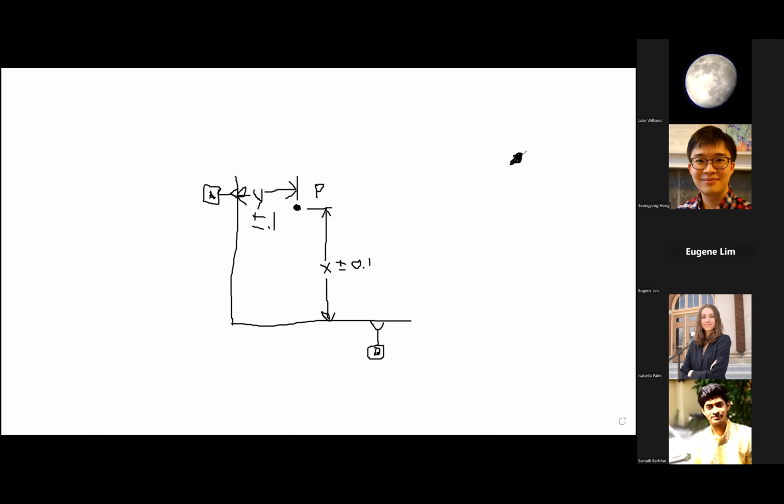And let's say this dot that I just drew is where point P would be if you were perfect, if you had zero margin, if you machined it perfectly. So you wouldn't need any tolerance, you had a perfect location. Now let's draw a box around here that shows the location that would be within tolerance.